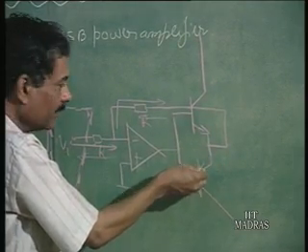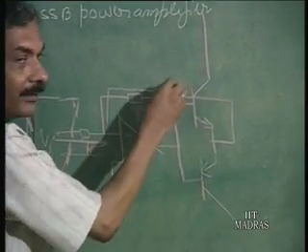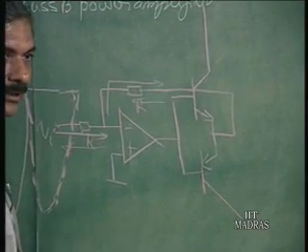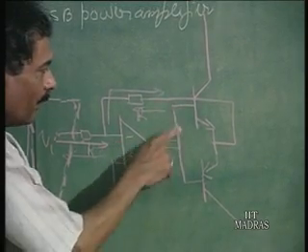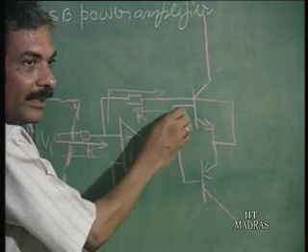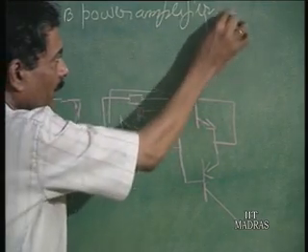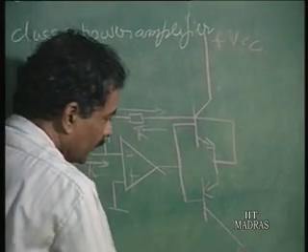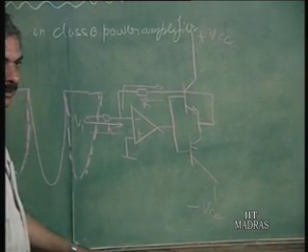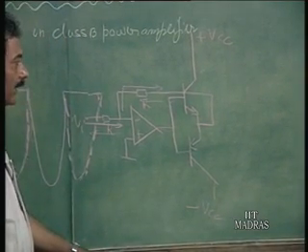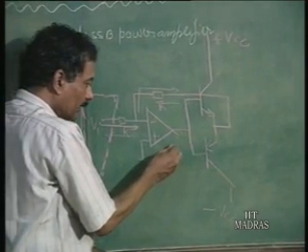So it is equivalent to the same circuit, only thing is we have R and 2 diodes connected in parallel. But as far as the op amp is concerned, it has to feed only the base current in order to retain the transistor in conduction. So the basic principle of this structure is exactly similar to what we have just now demonstrated of the precision rectifier. If you see the waveform at the output of the op amp, it will again be a square wave like thing.